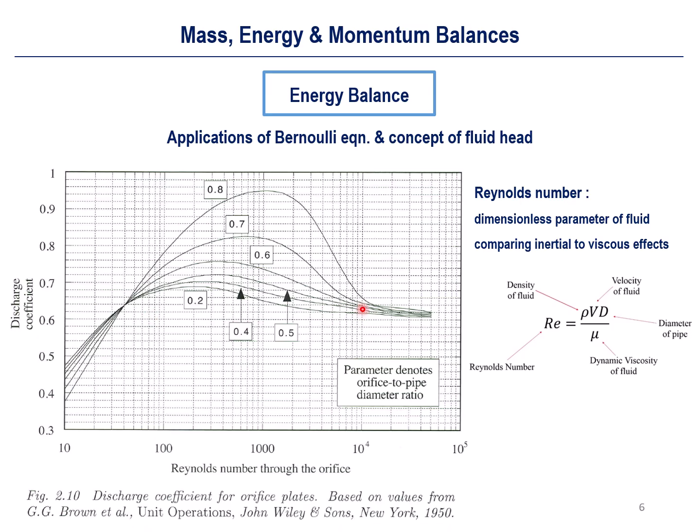And as you can see in this plot, which shows the discharge coefficient as a function of the Reynolds number, they have different profiles depending on the orifice geometry. So it is important as a chemical engineer to set this discharge coefficient as a function of your Reynolds number and your orifice or manometer geometry.